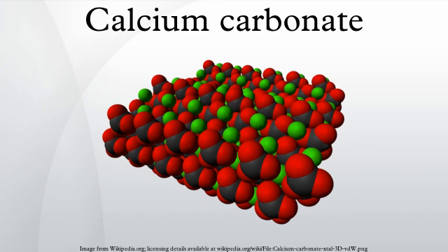Fine-ground calcium carbonate is an essential ingredient in the microporous film used in babies' diapers and some building films, as the pores are nucleated around the calcium carbonate particles during the manufacture of the film by biaxial stretching. GCC or PCC is used as a filler in paper because they are cheaper than wood fiber. In terms of market volume, GCC are the most important types of fillers currently used.